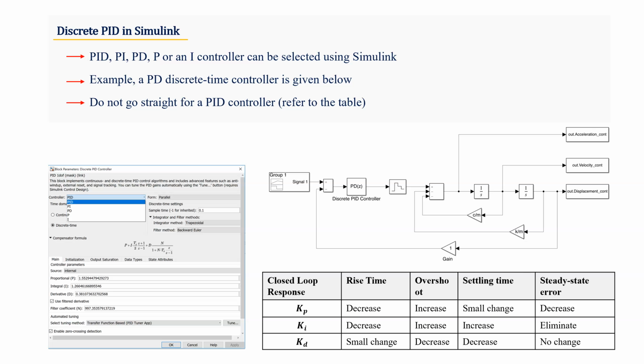And what will happen is, as a result of increasing the proportional control gain, you're going to introduce more overshoot, but it's going to minimize the steady state error. It won't eliminate it, but it will minimize it. So there's a bit of a trade-off in terms of minimizing steady state error, but consequently you introduce more oscillation.